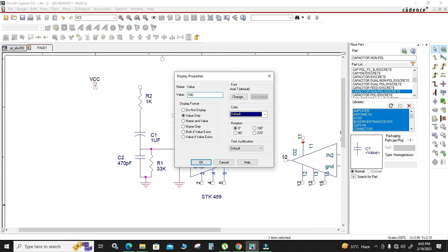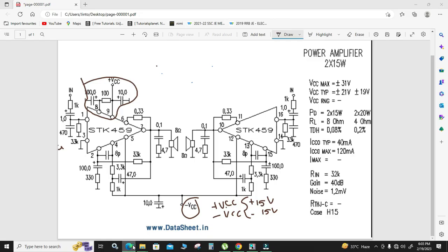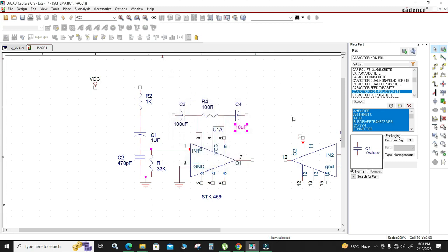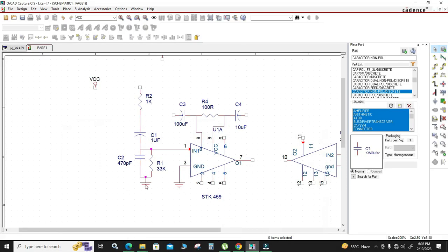In ohms, we use E or R. I'm using R, is it better? Yeah. Designated R4 is nice. Let's see. Yeah. Then the last right side capacitor is 10 microfarads. Again, using 10 microfarad, the U is a smaller U. Yeah. Value completed. Then the other side of these capacitors, both sides are grounded.